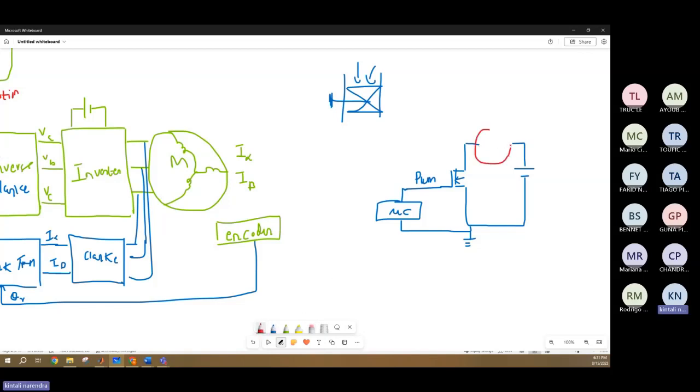In a different application, you might have a bulb also. In this case, I used a motor. Now, this microcontroller, with the help of the knob which I have at the microcontroller, I am controlling the PWM signal which I am providing to the MOSFET. So if I turn the knob completely, then PWM cycle will be 100%. Then there will be flow of current at a very high. If the knob is less turned, then the PWM signal will be less. Then the amount of current flowing into the motor will be very less. So the speed of the motor will be very less.